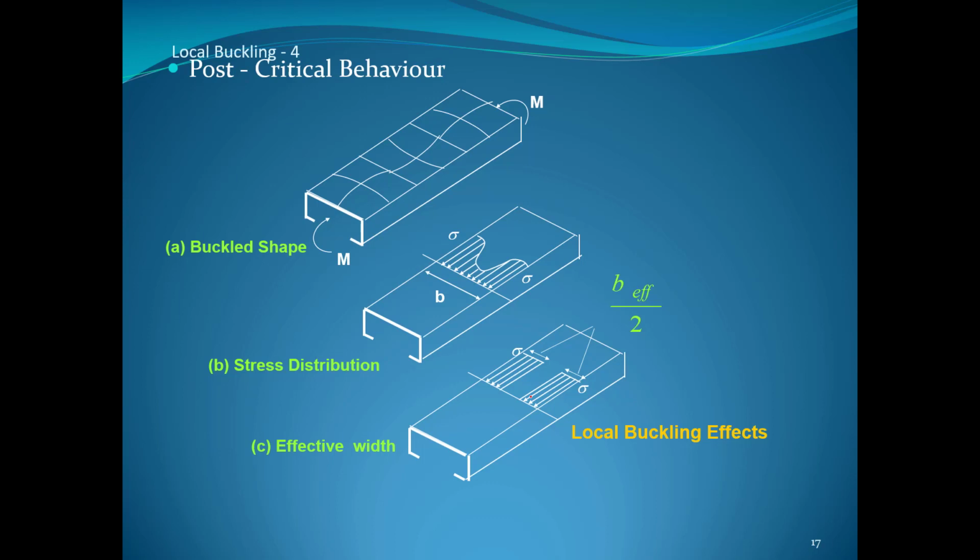And there is a term called the effective width method, which we have discussed before. Please note that when the channel section is applied with compressive stresses, for considering this element, this big plate, these are edge stiffened, like there is stiffening on both the edges.